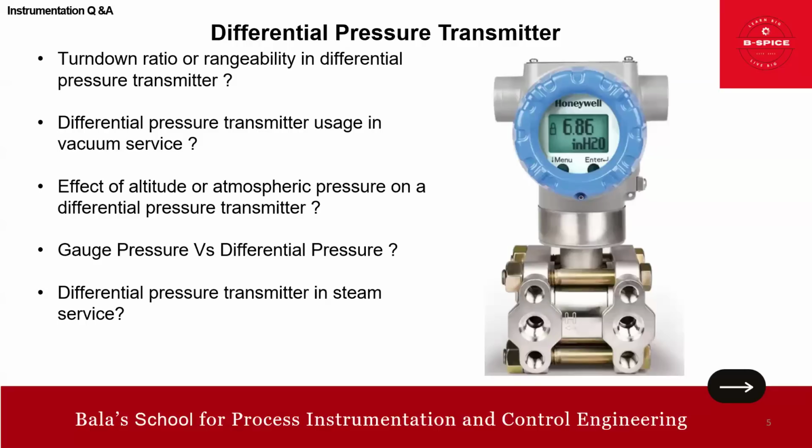Differential pressure transmitter in a steam service. Yes, we can use it. Of course, we need to take care of the steam temperature rating, all these we should focus on. And also the diaphragm seal you are selecting should actually withstand it. All these we should focus on.